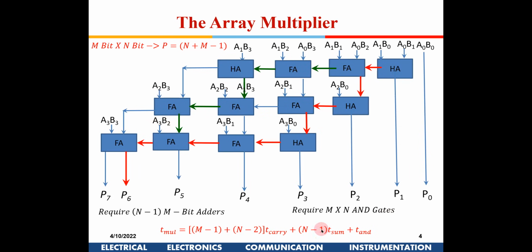So this particular circuit has multiple critical paths, or you can say that almost all the blocks are kind of critical. So for this particular topology, if you have to optimize it, then you might have to optimize each and every block. That will result in high power consumption, right? If you try to target the delay of each and every block here, so that is when we see other topologies, we will see that is not the case.